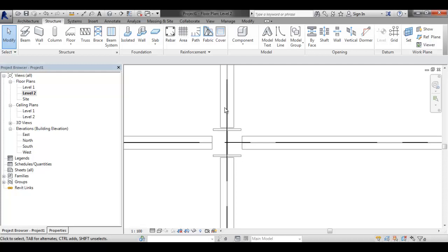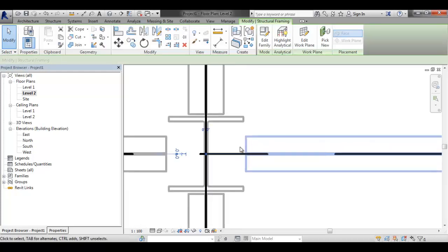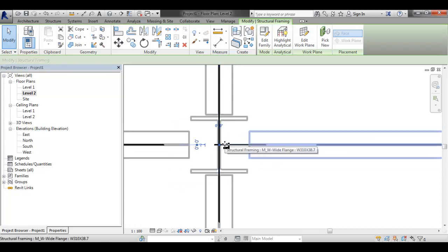So Revit by default will leave that gap open for you to allow you to make that connection, and you'll load that connection as a custom component. So you'll actually have to model what kind of connection you want. You'll model like an L channel that gets welded. Could be a gusset plate, could be whatever you want it to be. I'm not going to get into it. If you're like me, sometimes I just want the drawing to look like I want the drawing to look.